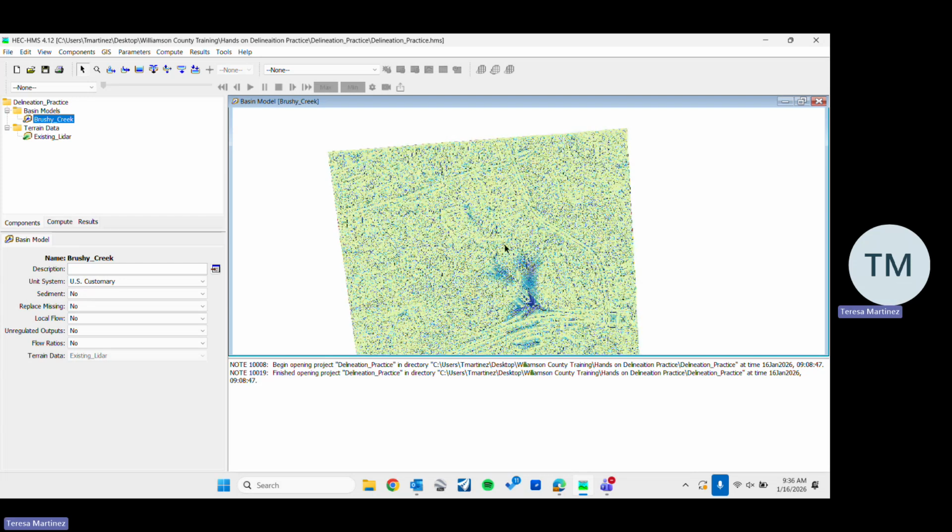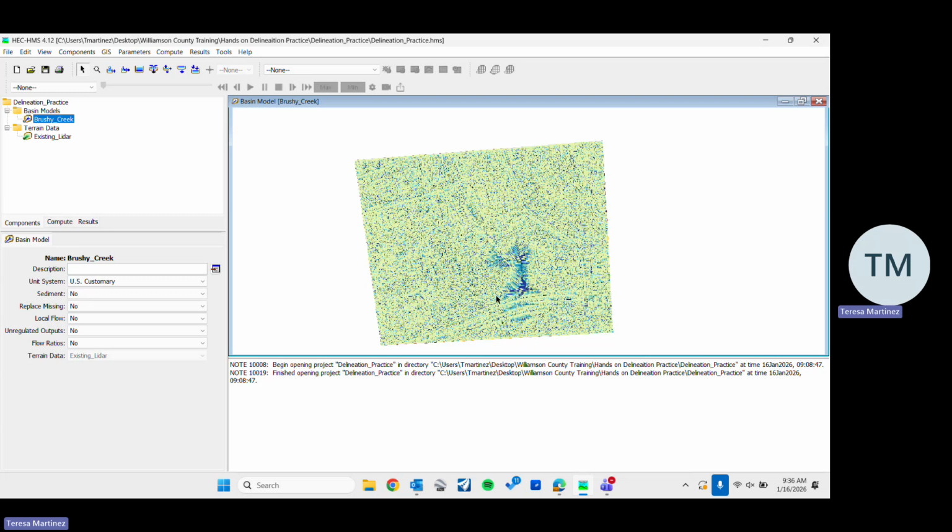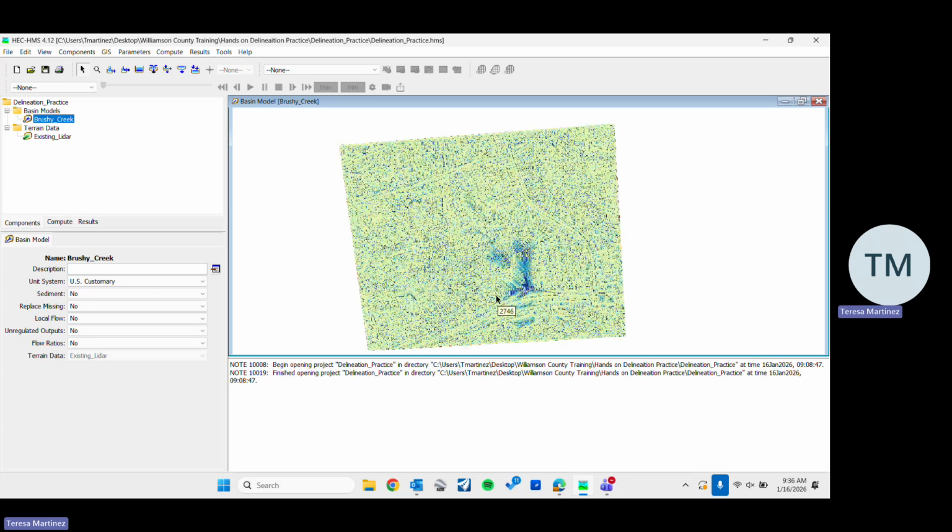One other question I have for you is, when we first used to do aerial flights to get the Z elevations, we would also send people out upstream to pick up however many sections we needed in HEC-RAS to physically shoot the bank. Part of that, I think, was because depending on where we did the flight, there might be vegetation. So in this LiDAR data, is it picking up the ground and not the vegetation? I have to assume it's getting the ground.